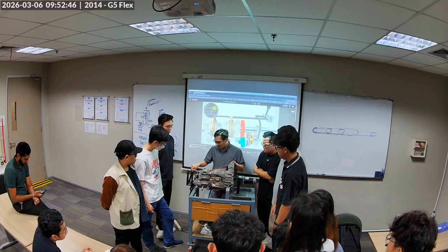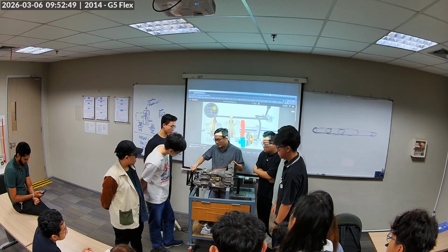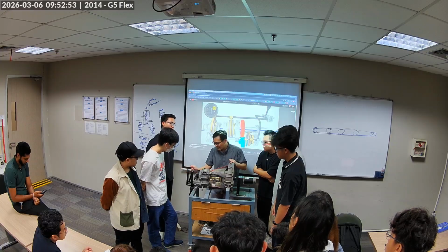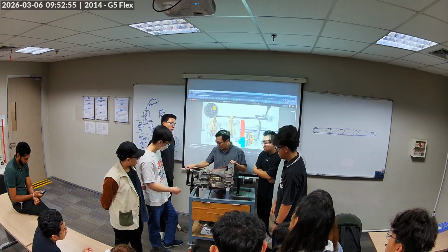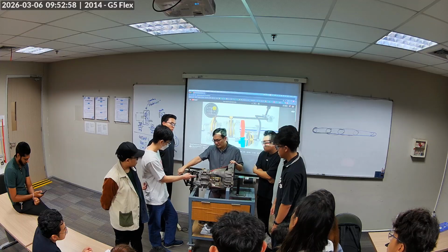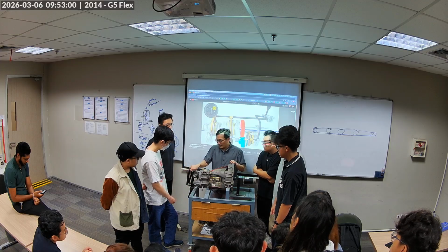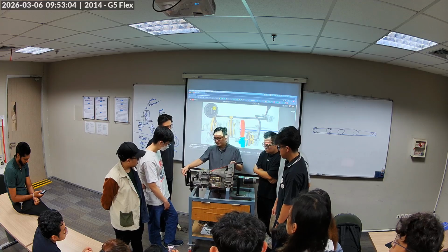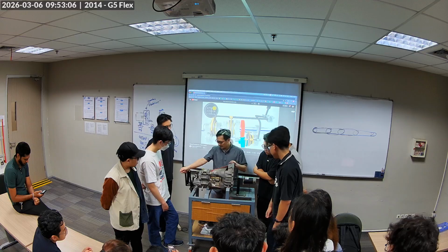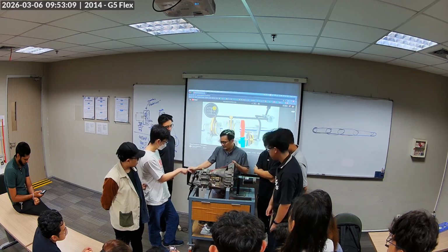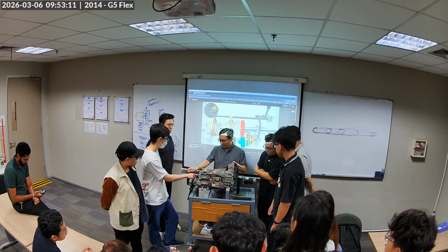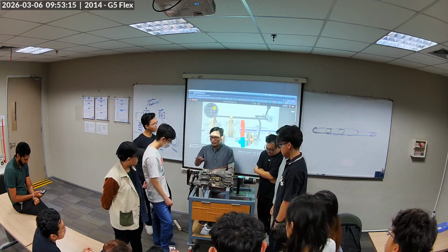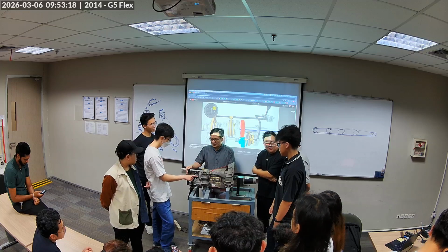And this is the second, okay? Slightly slower. So notice this is the first, slightly faster, yeah? Faster. And then the third is even faster. Fourth. And then fifth. And then reverse goes the other way. Yeah, the ratio of reverse gear is between 1 to 2, between the first and the second gear.